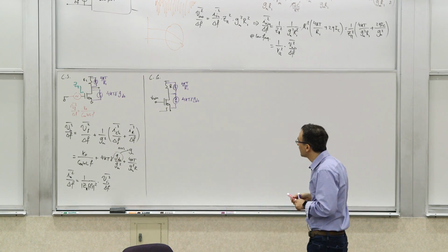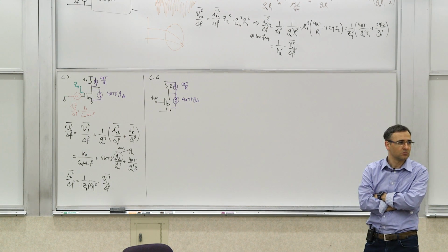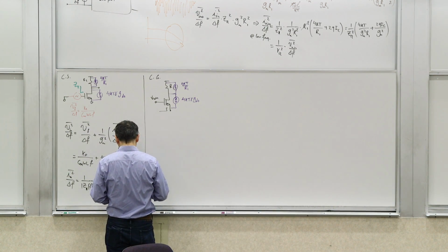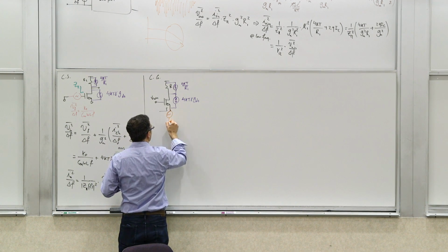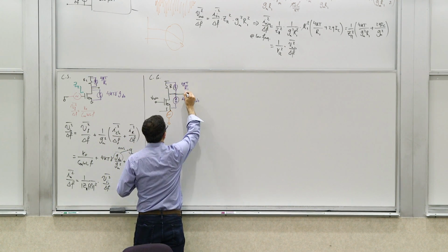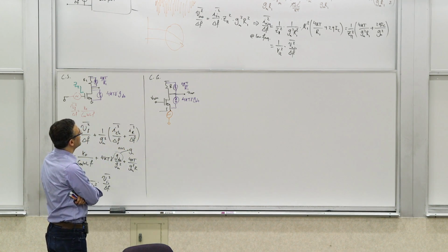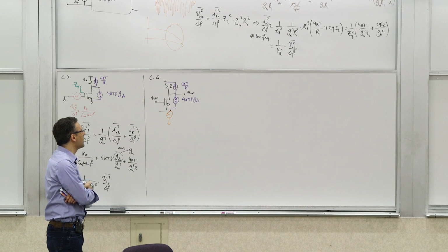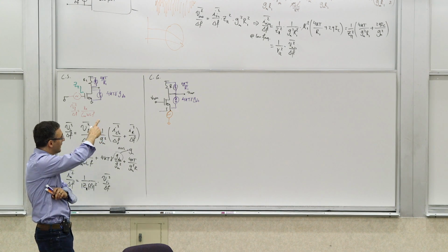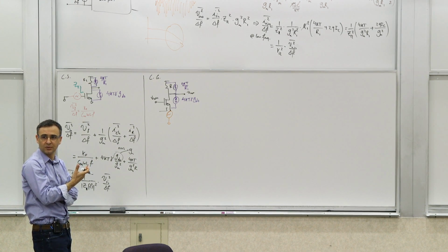So what is the input referred voltage noise source? It's the voltage source you need at the input to generate the noise at the output that we anticipate to get. So what is that noise if you have a voltage source there? Let's use superposition of the two purple ones. Each one is injecting a current, 4kT gamma GD0 and 4kT over R1, into that node with a resistance R1 to AC ground.